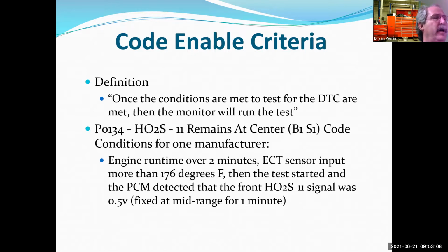But that's also why you always, I'm going to put a new sensor in it and retest for proper operation. Now I get the same result with the new sensor. Now we know we got something weird going on. Bad PCM, something weird in the wire, something weird. Now we got to get to the PCM that might not be easily accessible, get to the wiring. I got to check signals at both ends. Now I'm using a couple channels of a scope. I mean, that's another hour or two diagnosis.